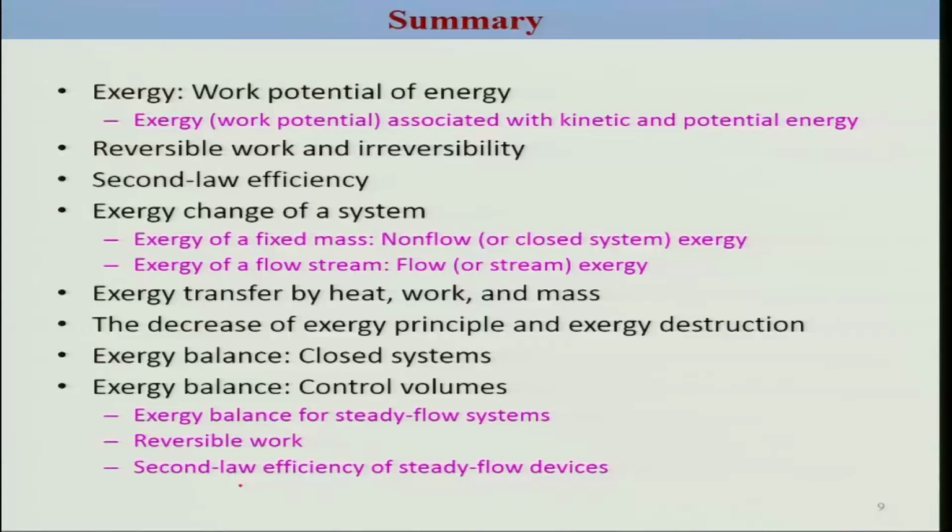So let me just summarize what we have gone through in this topic on exergy. We defined exergy, which is nothing but availability, available energy, or useful work, or work potential of energy. Okay. And we also looked at reversible work, irreversibility, and second law efficiency. We made use of exergy in this. Okay. We defined exergy change of a system for non-flow and flow systems. Exergy transfer occurs by heat, work, and mass. And then we defined that the decrease of exergy principle is also equivalent to your second law of thermodynamics. And we also defined the exergy destruction, which is related to entropy generation.